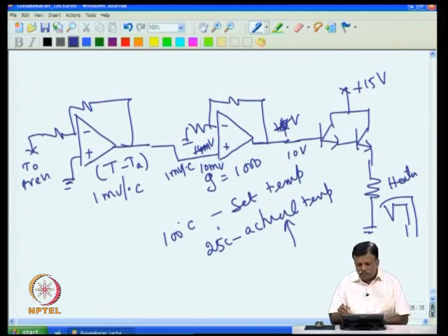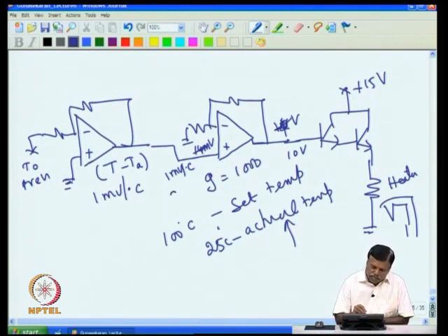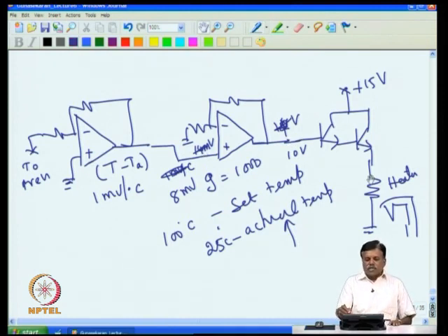Now heating comes down further, because now we are applying 10 volt minus 1.2, that is 8.8 only. Now if the heat is still higher, to maintain this at 100 degree C, this will still go up. This will come down, because the temperature will go up and the difference will come down, and this will come to say 8 millivolt. If the difference comes to 8 millivolt, this will go to 8 volt, and this also will come down. So as the temperature rises, this voltage is coming down, and the heater voltage also comes down, and it produces less heat.